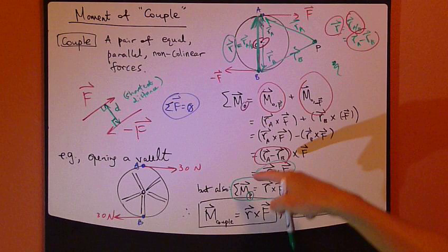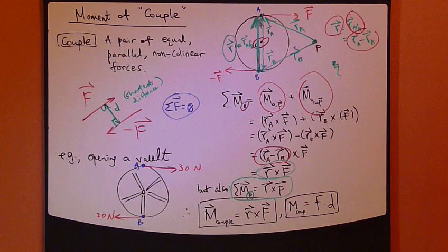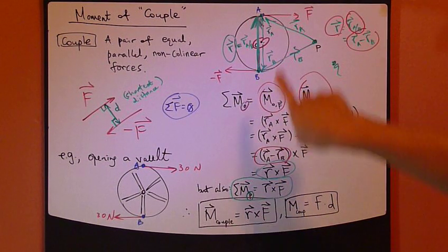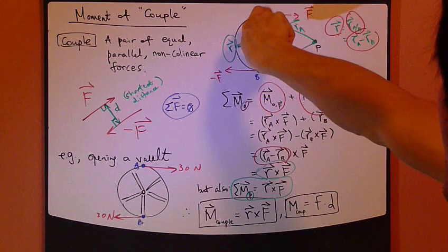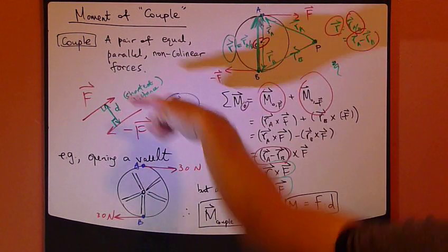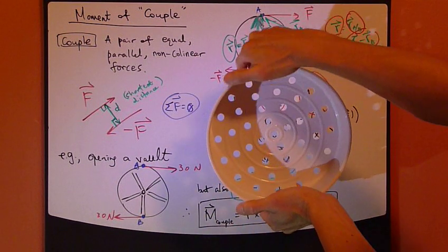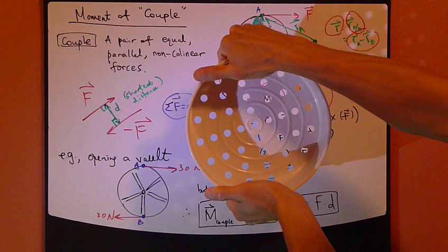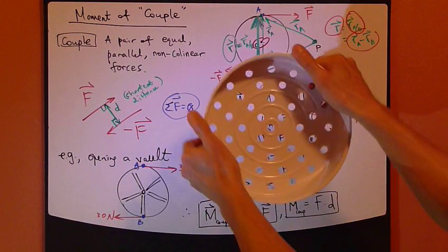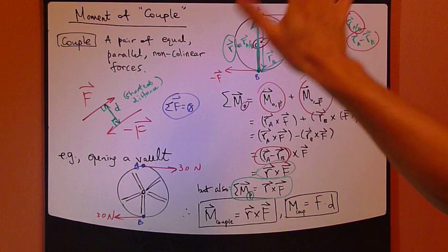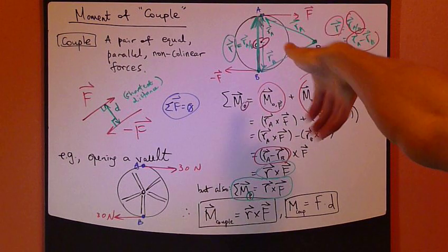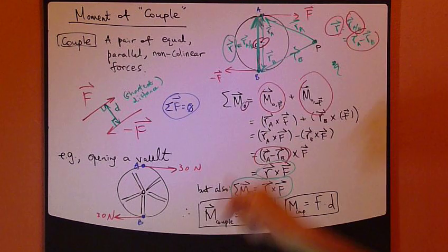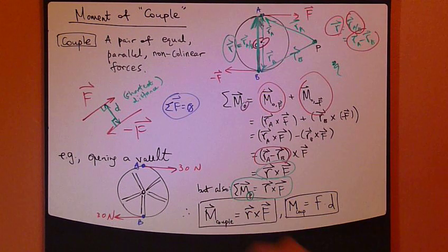As for the sign, or the direction of the couple M, you just look at the direction of the F. Look, it's right here. F on top going this way, F at the bottom going to the left. Again, this has the effect of wanting to make this valve or steering wheel, whatever it is, rotate clockwise. Using the right-hand rule, for clockwise rotation your thumb is pointing into the board, into the paper. So that would be the direction of the couple M.